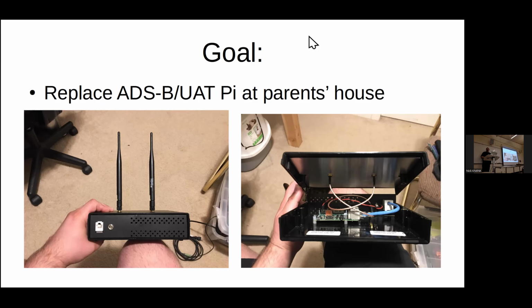It doesn't give you any information about what the aircraft is, where it's going, anything like that. Secondary surveillance radar sends out an interrogation pulse, and there's a transponder on the aircraft that will respond with its squawk ID, its ID code, altitude, and a few other things.